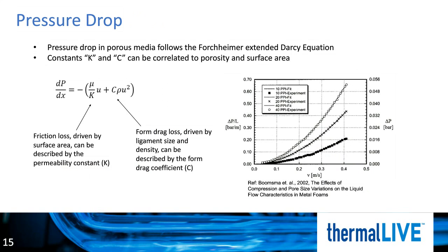Lastly, one must usually consider the flow resistance or pressure drop through the foam. Experimental data for fins and other conventional extended surfaces is usually cast as a friction factor. While the same can be done with foam, more convenient correlations make use of porous media theory.